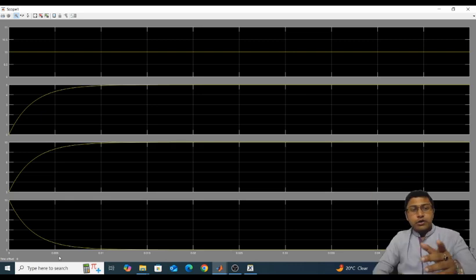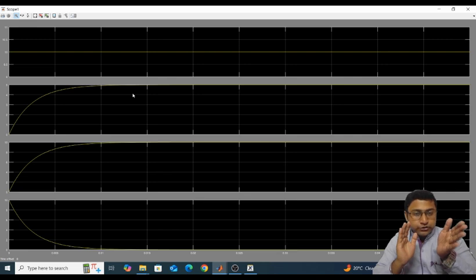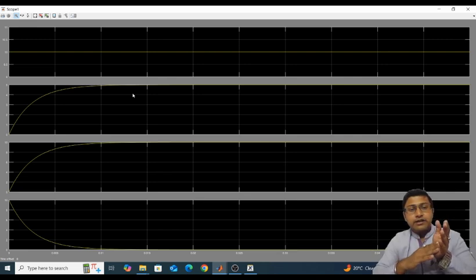Here, the steady state value of the inductor current is 5 ampere, of which 63.2%, more or less, is 3.16 ampere. You can check it in your own calculation. Now we will show that the inductor current at 2.5 millisecond reaches 3.16 ampere. That is the concept of the time constant.